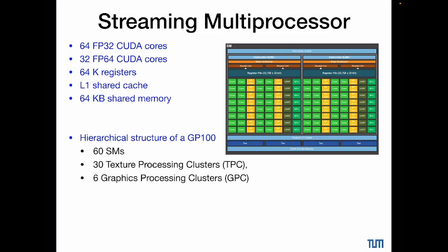The scheduler, which is somewhere over here, selects an instruction and it will be executed on all these 32 cores in lockstep, right? So it's like a SIMD unit that I explained in standard processors. Now they also have specialized units, special functional units, load store units and so on, so we don't need to understand this. But what I want you to memorize is that it's optimized for data parallel processing. And it can do it very fast.